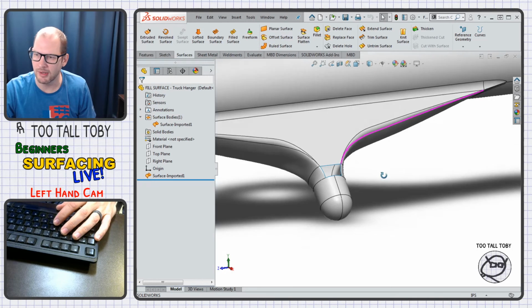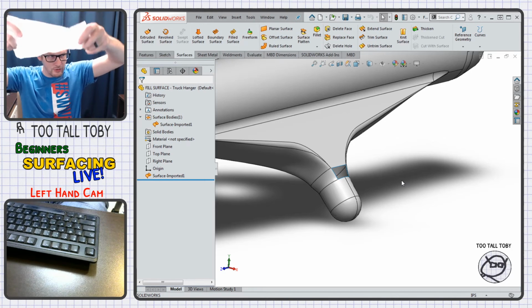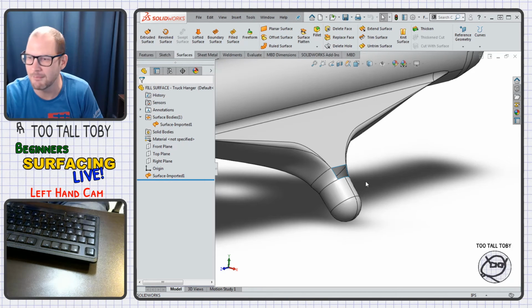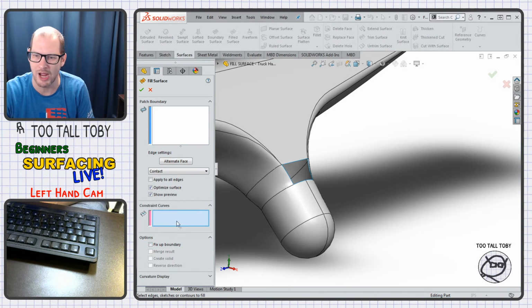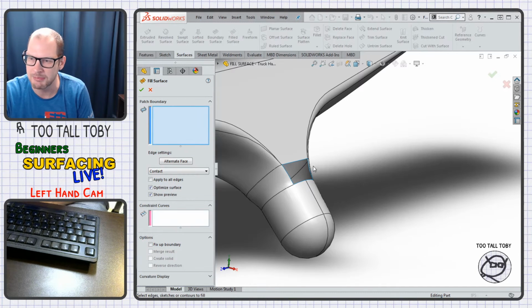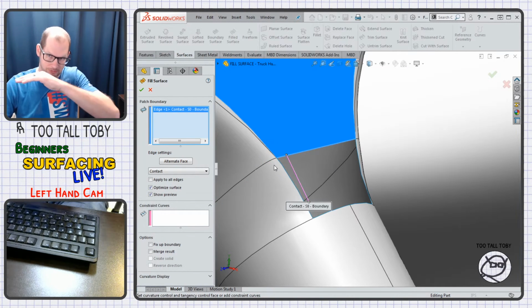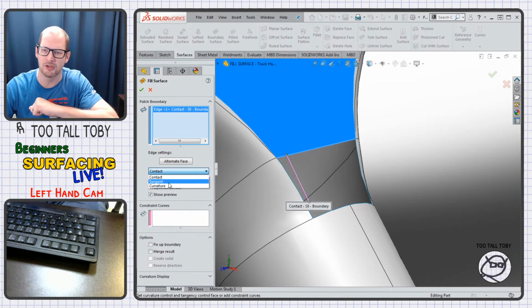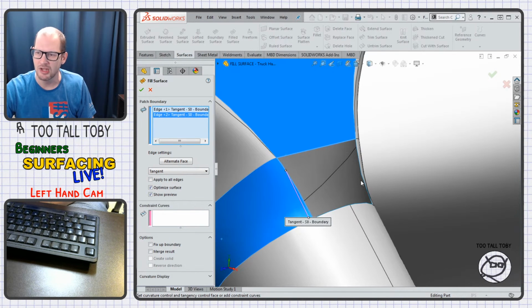And then what we want to do is take that example of taking the blanket and laying the blanket over the open geometry. So that's the example of using the fill surface. And you saw a moment ago, there's all kinds of extra stuff we can do with fill surface that we're not going to get into today, like when I dropped in that constraint curve, or there are options for how I'm going to be connecting to this edge here. Is it just going to connect right to the edge straight, or do I want to enforce a degree of tangency to that existing edge so that I end up with a smooth result? Maybe this edge here, that would be really important. Coming off of this edge, I don't want it just to be a flat spot. I want it to be tangent to that edge.